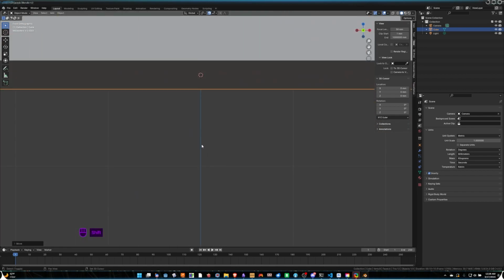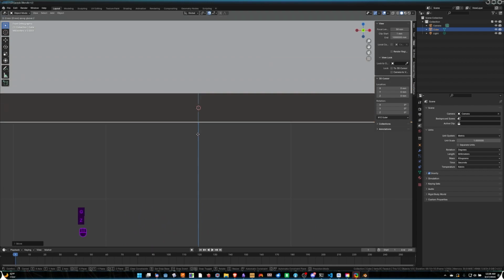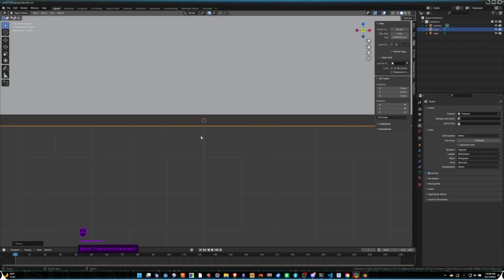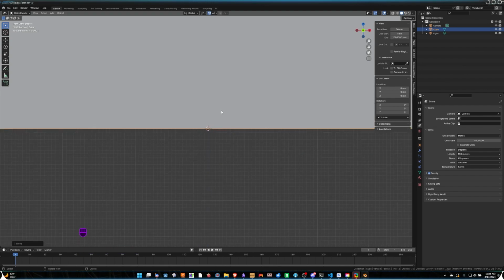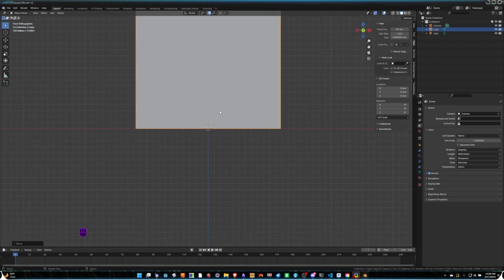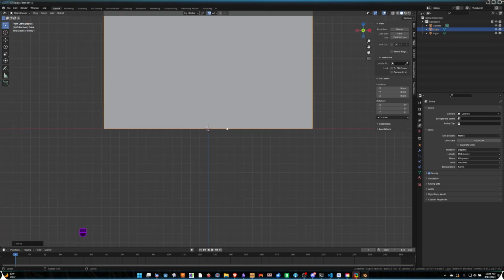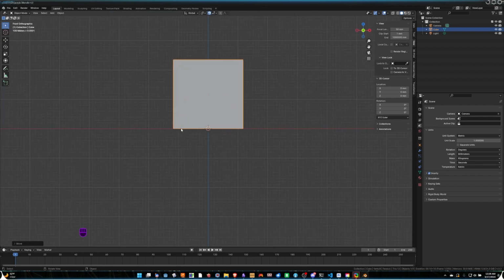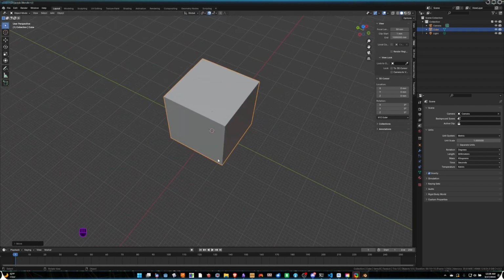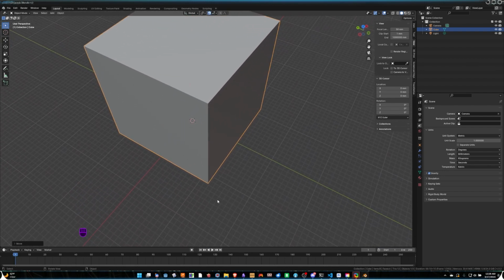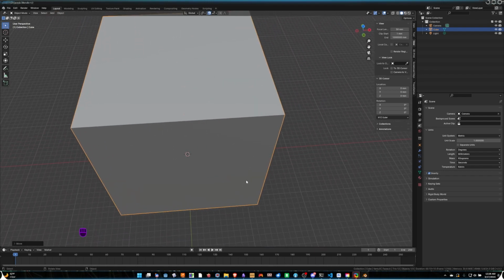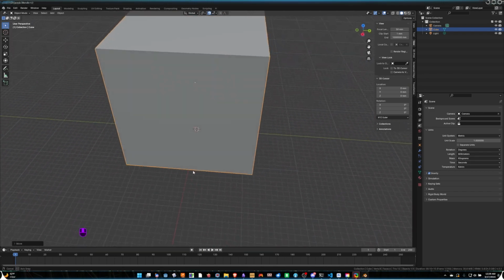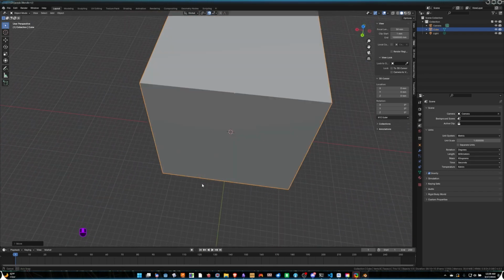Now you might notice that this is actually cutting off one of these squares, and we're not getting the precision that we would hope for. Well, that's because we're in 235 millimeters and it's splitting a millimeter to put the center of our cube in the center of the world. If we had a 236 millimeter area, then it would be different. But we've got 235, so we're going to have to settle for about 0.5 millimeter on either side of the cube. So it's going to split one of our grid squares, and then it's centered. So that's what that looks like.